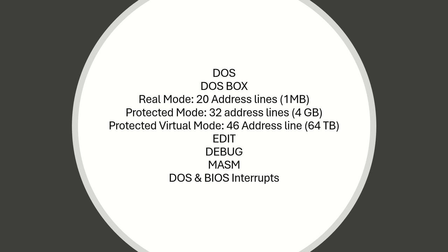So it is compatible to all the peripheral chips like 8255, 8251, 8237, 8254, all those peripheral chips. So that is the popular addressing capacity, what is called real mode. Real mode means 8086 mode, which is having 20 address lines. The addressing capacity is 1 megabyte.